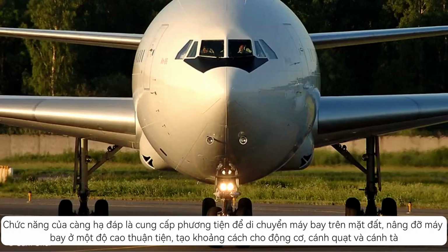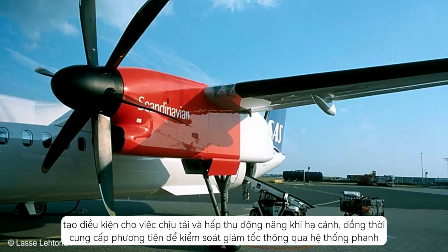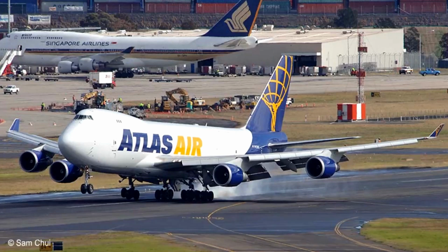The functions of the landing gear are to provide a means of maneuvering the aircraft on the ground, to support the aircraft at a convenient height to give clearance for engines, propellers and flaps, and to facilitate loading and to absorb the kinetic energy of landing and provide a means of controlling deceleration through the brakes.